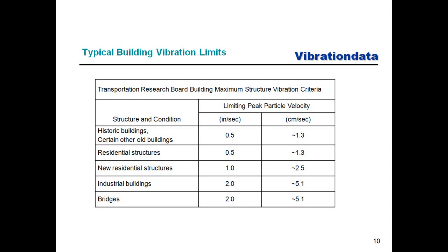Now, the concern here, for example, is let's say there's a building, and outside that building there's a busy roadway, and large trucks are coming up and down that roadway. Well, that generates ground-borne vibration that can affect that building. There's also another concern: what if there is a construction or demolition of a nearby building? Well, in that case, there's going to be a lot of vibration due to the construction, and that vibration will also be transmitted via the ground into the foundation of that historic building. So there are different concerns there.